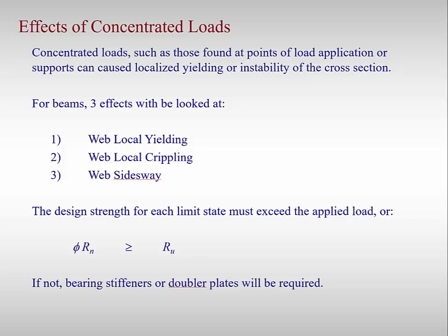As with any design, the design strength must exceed the factored design load or demand. Here we will use capital R sub n for the nominal strength. If we do not have sufficient strength, transverse stiffeners or doubler plates can be used to increase the web capacity.